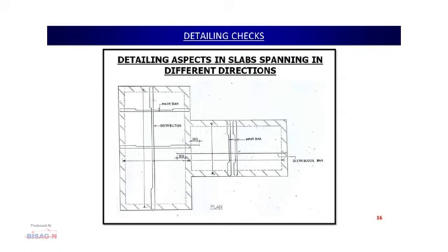So, we have to first understand in which direction the slab is bending and what the structural designer is actually showing in the drawing, and you have to follow this meticulously. Again, you have to ensure whatever reinforcement is crossing this and coming into the next slab should be given at least a 300 mm length inside the next slab in this direction, and this bar which is coming should be given in this direction. So, with this I conclude this lecture. Thank you.